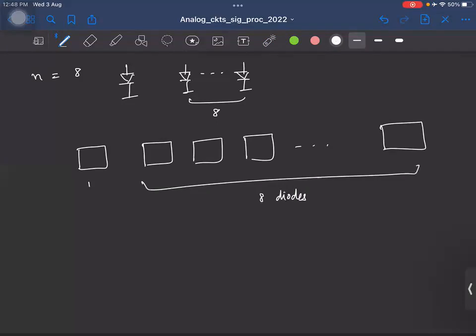You guys have done layout before, right? So you guys know. See, finally, if you take any IC, you will not have the same environment throughout the IC. For example, you will assume that your P substrate is doped with some doping concentration, but you'll always have some kind of a profile. For example, towards the left, you might have a larger doping concentration, and it might decrease as you go to the right.